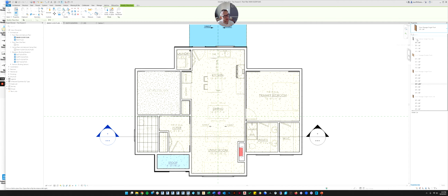And then underneath each family, so see there's this family, 1, 2, 3, 4 families. And then each family has different types. Those are the different sizes. So this family has glass in the door, and then all the different types are the different sizes. This is a double door, and then these are the different sizes. And you only have what was loaded into the template.